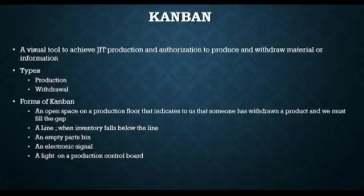After the value stream is defined through standardized work and flow has been established with the help of 5S and Poka-yoke, the next step is to use a pull approach. Kanban is used to demonstrate the pull approach on the Bosch Rexroth workstation. On the workstation, we have used color coding on the flow rack system.